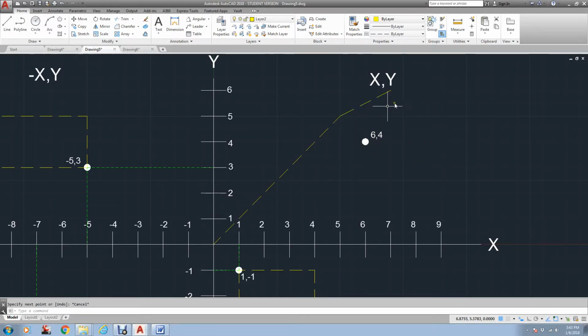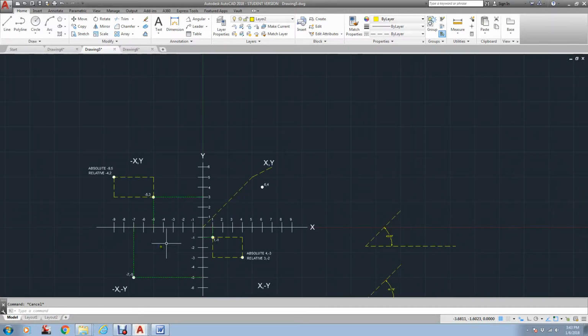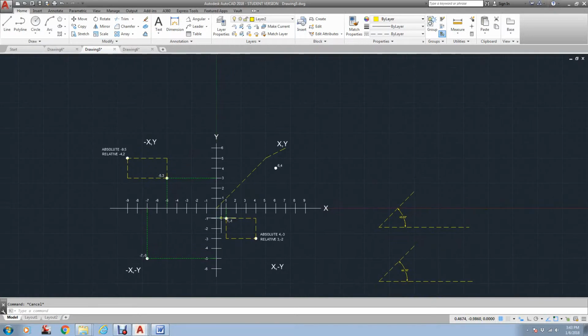Went over 2, and yeah, there it is. 1, 2, and then went up 1. Down here, this would be the absolute 2 and 1. So by inputting it up here, right up here where all this lettering is going, this is your dynamic input. It will always be relative. When you're doing absolute coordinates, you input it down here at the bottom. Okay, that is a big thing.